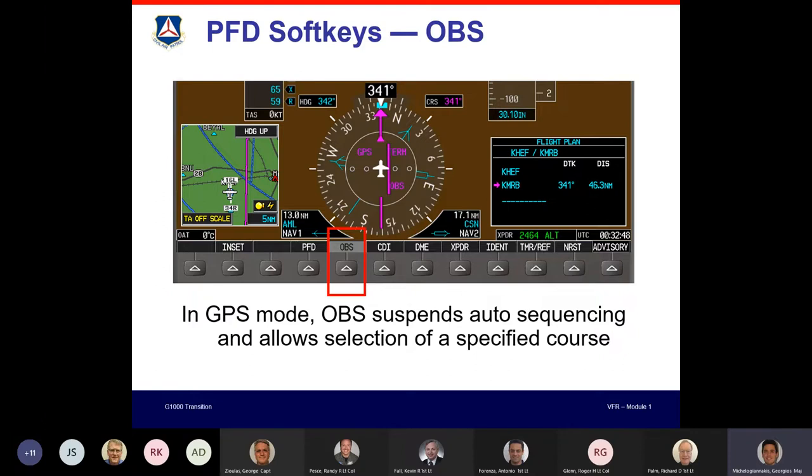For example, if you want to fly the ILS 28 right at Oakland, that approach has you use a DME from the Oakland VOR, even though you're flying a localizer. So you have to set it up right so that you get an inset showing you distance to the Oakland VOR, say by putting the VOR in NAV2 but flying the localizer in NAV1.